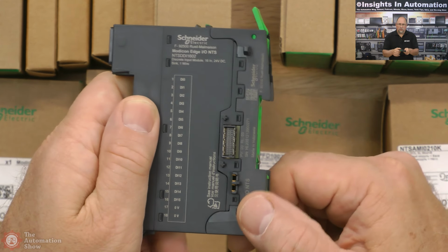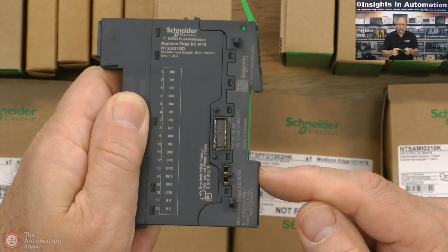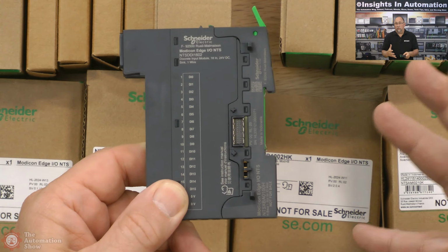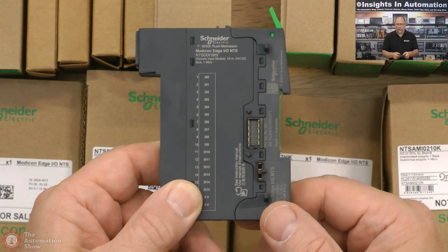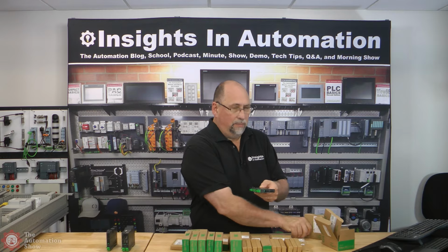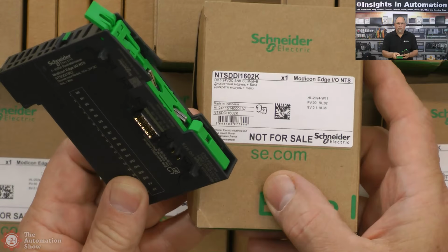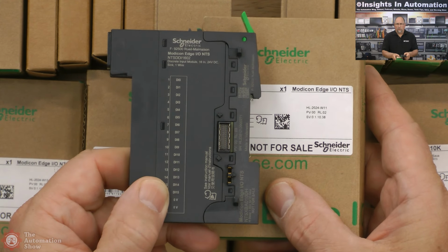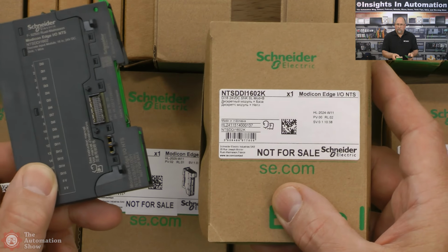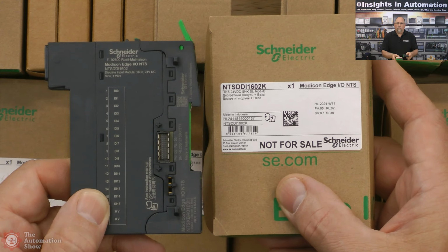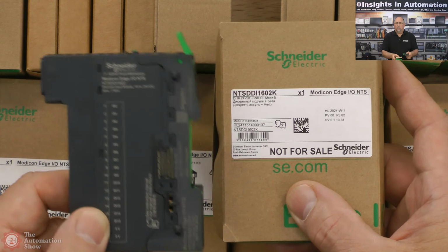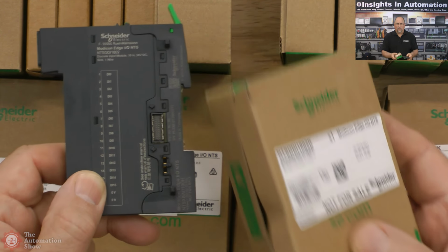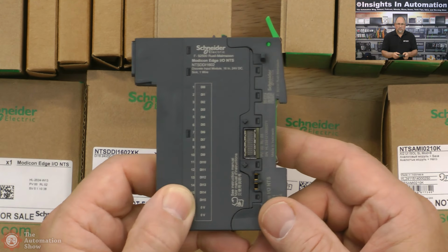Now you'll notice this is actually two different parts here. We have this base, and then we have the I/O module, and that's so that if you wanted to replace one, hot swap it, you can. The system does support that. If we come back out here and look at the box, you see that K at the end? That means this is a kit. This has both the module and the base. If you had to replace a module, not that it would go bad, but who knows, you wouldn't have to buy the K because you already have a base installed. You could just buy the module itself. But I think most new applications, you're always going to buy the K because you're going to need both pieces to have a working system.